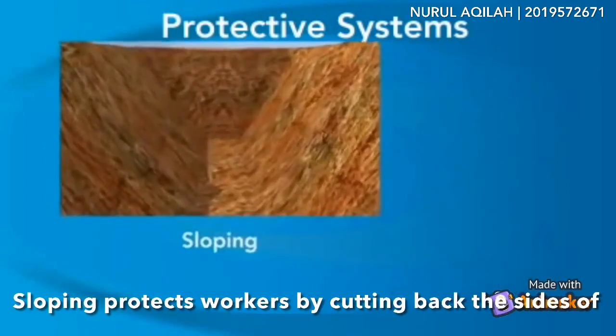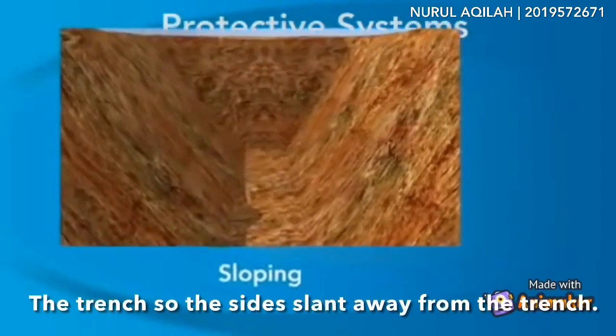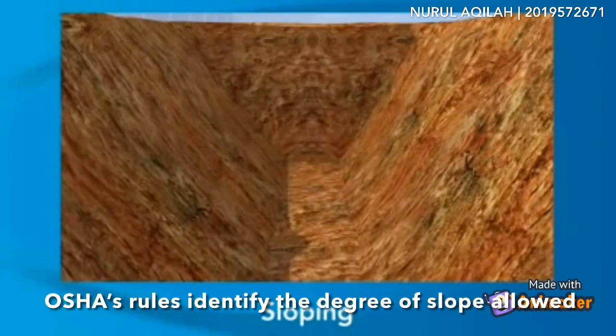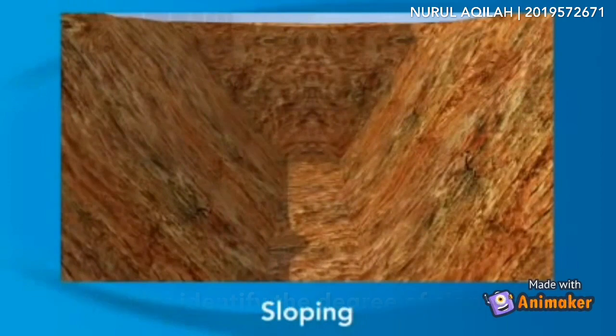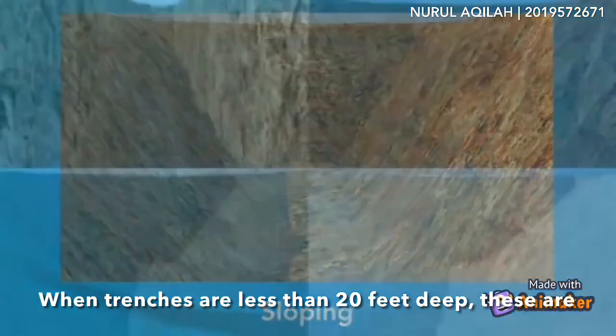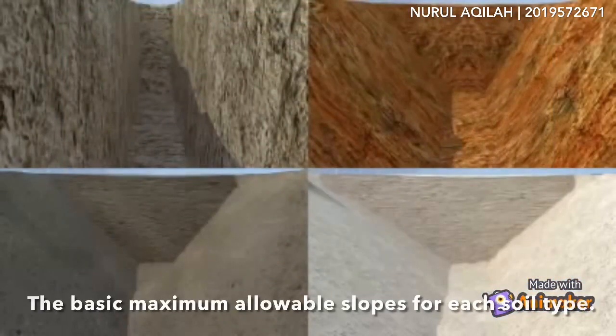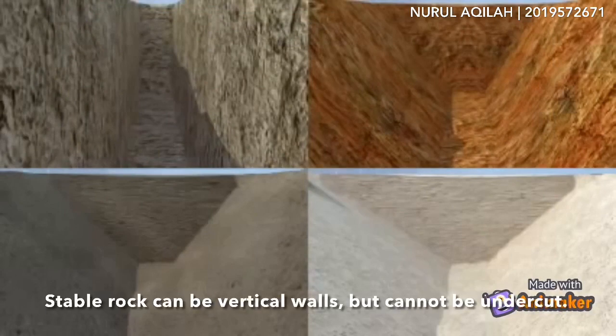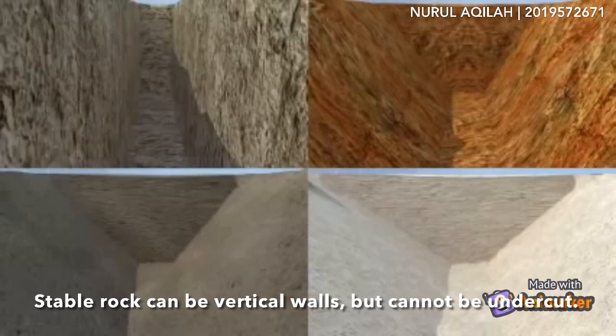Sloping protects workers by cutting back the sides of the trench so the sides slant away from the trench. OSHA rules identify the degree of slope allowed for each different soil type. When trenches are less than 20 feet deep, these are the basic maximum allowable slopes for each soil type. Stable rock can have vertical walls but cannot be undercut.